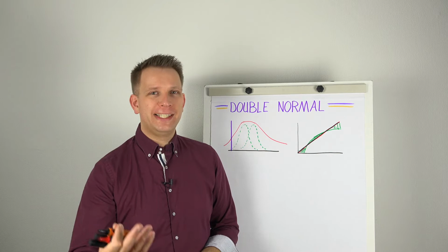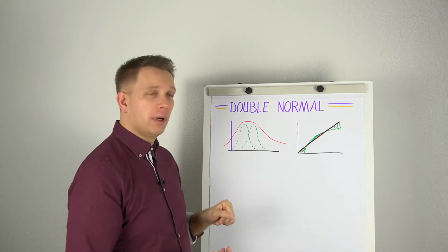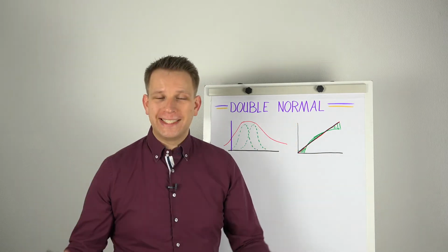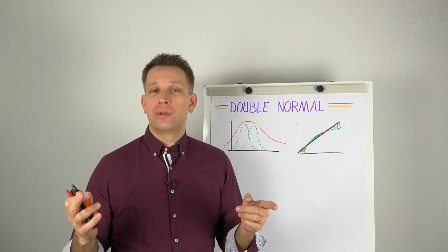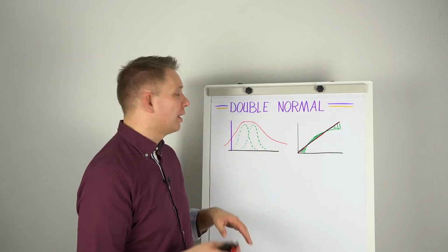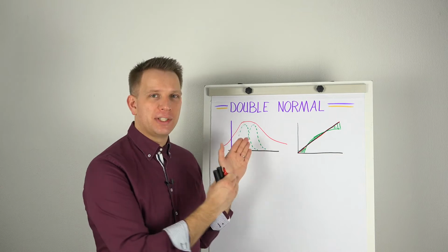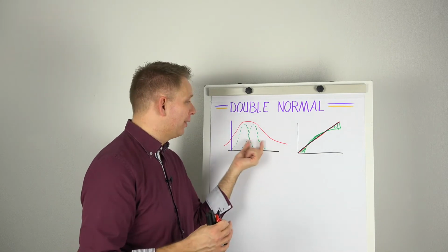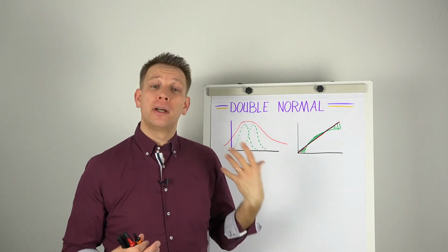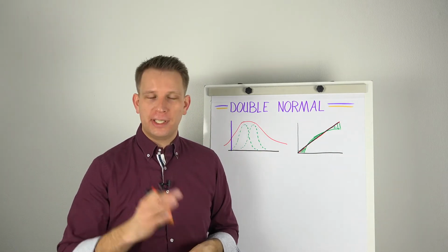And then there are all kinds of t-tests, but especially here the 2-sample t-test to check. We have a sample of all of our left nozzles, we have a sample of all of our right nozzles, and we take the average per nozzle, get also those standard deviations, compare them, do this 2-sample t-test, and check if those 2 samples are statistically just one big distribution. That is, the difference is negligible compared to their own spreads. So if they have a very wide spread and the difference is relatively minor, your t-test will say just treat it as one population for purposes of statistics and normality.